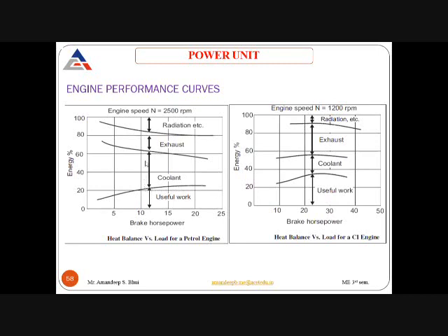Now above this graph, you can see the graph for how much heat is being taken away by the coolant from the engine. At the start, when the engine is cold, the heat taken away by the coolant is more, and as the engine starts to work under working conditions, this energy taken away by the coolant starts to reduce, because more power is available in the useful work region.